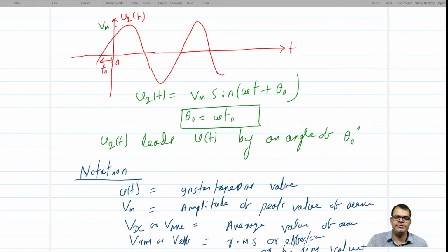Normally people confuse it with the average value, that the average value will heat a coil. But the heat energy, how do you calculate the energy for an AC? Obviously from the RMS value. From that you should understand that heating value is the RMS value.